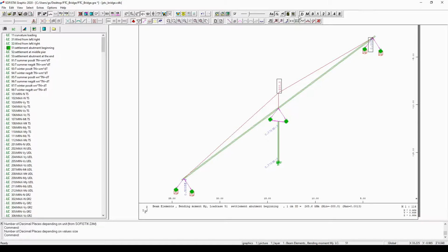The next toolbar I would like to talk about is the decimal toolbar, on which you can set the number of the decimal places. For example, if I click on the 0, there will be no decimal places represented in the view. If I select 1 decimal place to be represented, then as you can see, the text changes, and really we can only find 1 decimal after the point. Or simply you can choose the engineering form, but the default is this .d, which means depending on the value, which follows an underlying rule for the best representation on the screen.